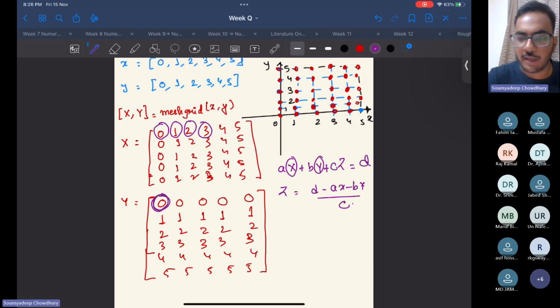You have named the function meshgrid, is it? No, you cannot use that, because meshgrid is a reserved keyword for MATLAB. You cannot use that as the name of the function. When you save the function, save it with some other name. Yes, I think that is creating the problem because meshgrid is a command.